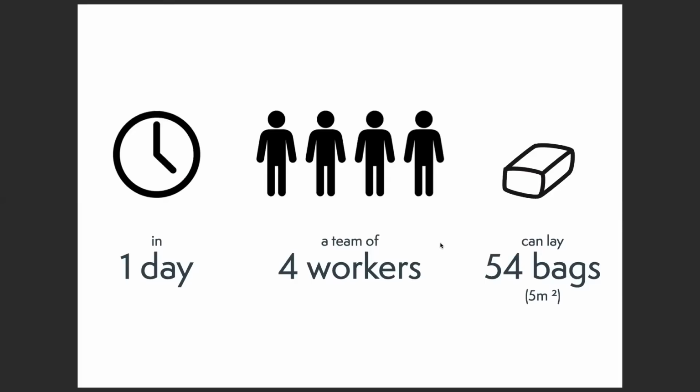Actually, I should just stay there because I wanted to ask you a question. When I explained the design, I think there's one significant aspect that I didn't mention, and that is the fact that our walls do not actually touch the roof. In the cross section you could have seen that, and when we go to site you will also see that. We have used that as a particular architectural measure to increase cross ventilation, to bring indirect light into the building, and also to emphasize this indoor-outdoor transition that we are keen on.